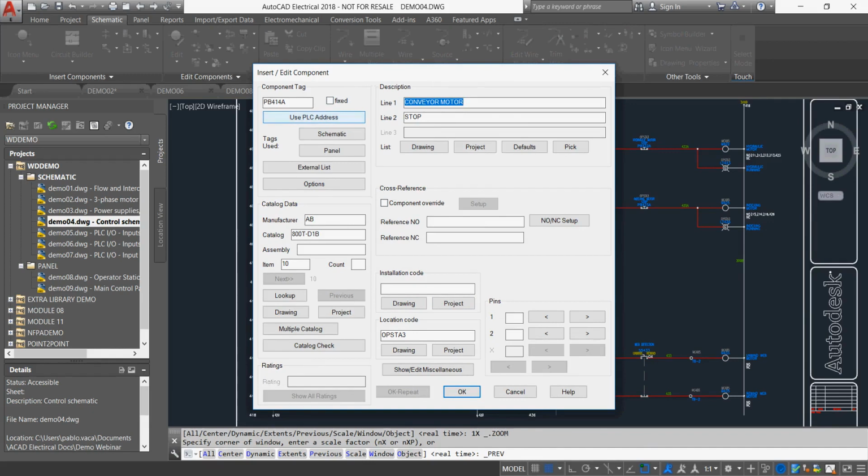All these are stored in a database which contains the information that is related to your electrical components and create a live bi-directional link between your schematic diagram and your footprint layout. As a result, this bi-directional link will allow you to automatically translate any changes that are done in your schematic design directly into your footprint and vice versa, so you don't have to spend time double-checking your work.